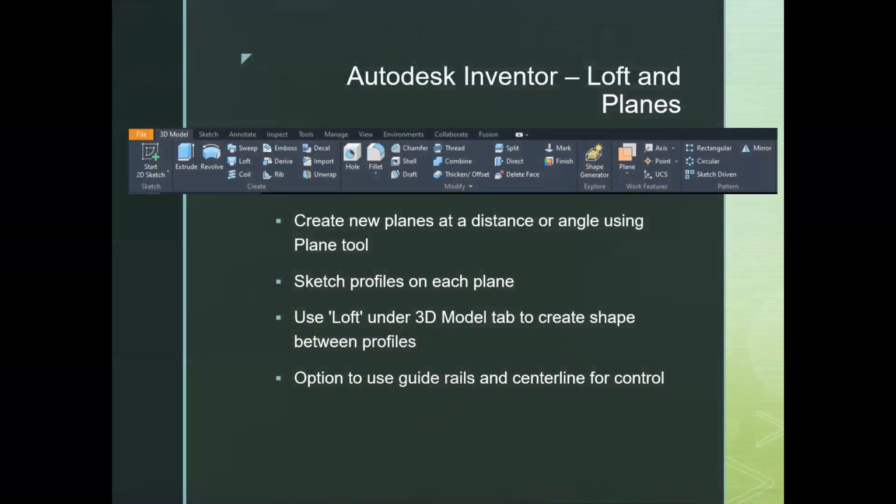Now, Inventor does have that dedicated plane, and it's also going to have the loft command. Now, the loft command is located here. Super simple to find. And the plane is going to be here. One thing that I do like about Inventor is that it shows you all of the options that you can use to manipulate and create a plane. And I'll show you that here in a second when we switch over to it.